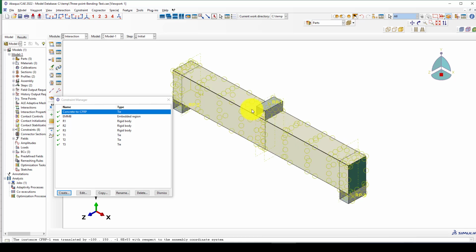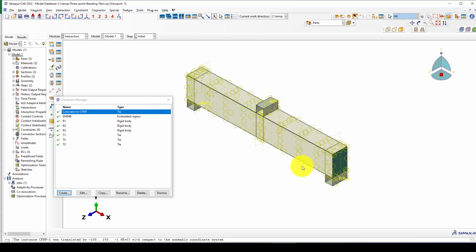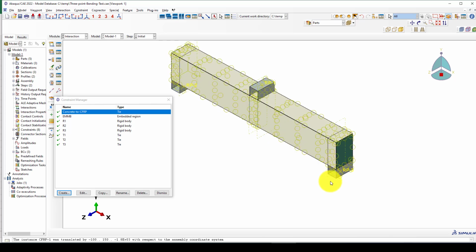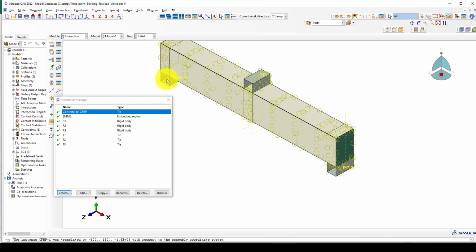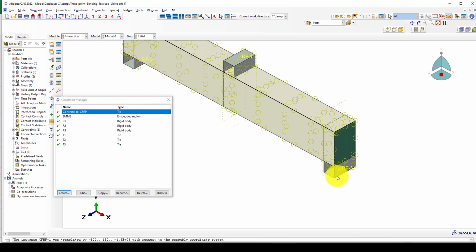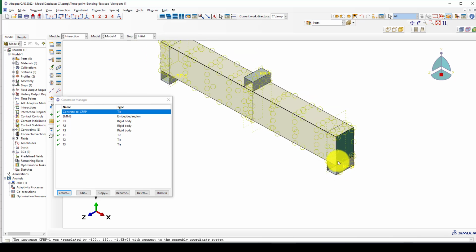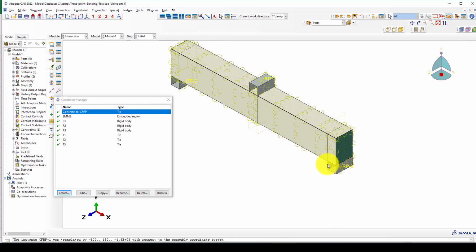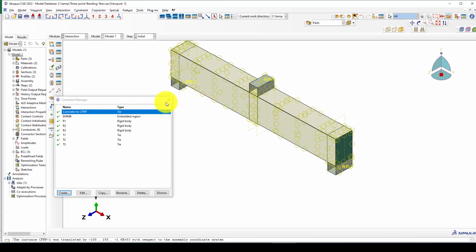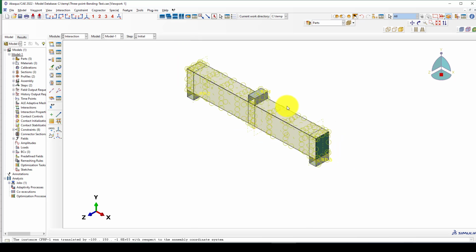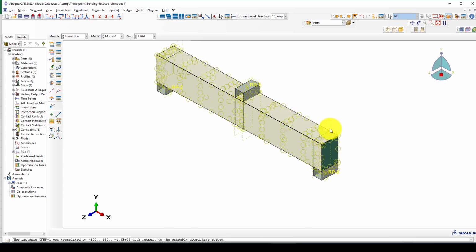Now here is one more thing, in case maybe we should change the connection between the supports and concrete, and also the connection between these discrete elements with the CFRP. It's okay in case we don't receive any error, so it's okay. Otherwise, we should change it. First, I ignore this and just consider the contact between these two. It should be the concrete. Now, here the interaction is finished.